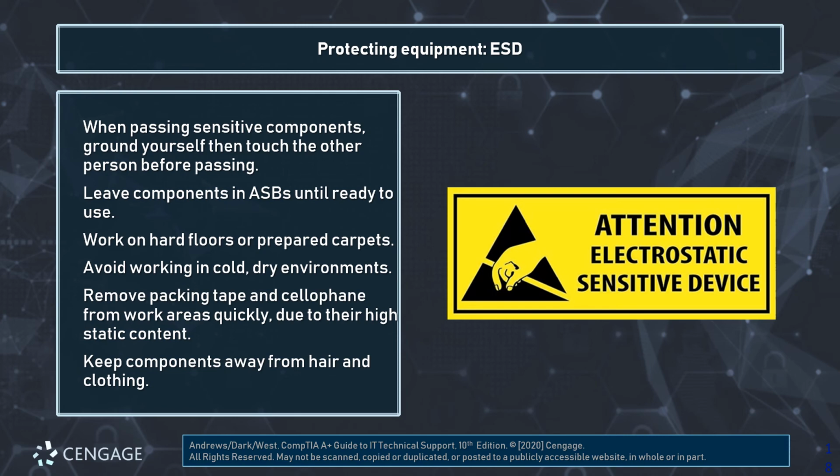Wearing sandals and things like that in the lab not only increases potential tripping hazards, but often doesn't have very good grounding properties. Avoid working in cold and dry environments. These are areas in which static is very prominent and very easy to generate. Remove packing tape and cellophane from work areas quickly because they're able to generate a lot of static.